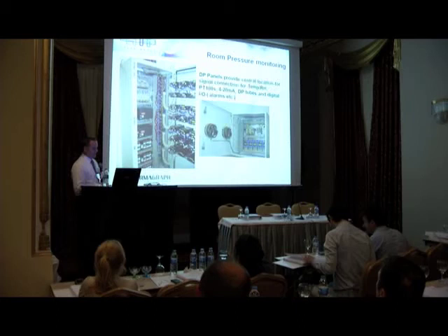The accuracy of the sensors is about 0.5%, plus 1% over range, and it's available in any range you want, really. Typically, if you're looking at 15 Pascal changes, I would recommend that you go for something that has a plus and minus range, because if you've got a room and you're looking for a positive pressure of 15 Pascals, what you're really worried about is the airflow into that room.